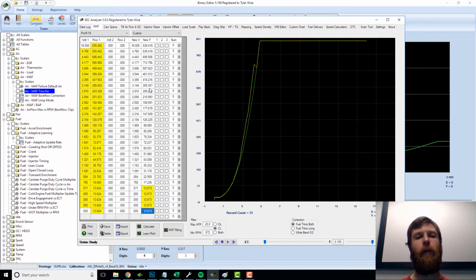So you're no longer running at 14.64 or thereabout, and that's all your factory oxygen sensors are capable of understanding and reading. So when you're in heavy throttle conditions, those sensors can't help you tune anyway. That's the whole reason you need a wideband oxygen sensor that can read that full range of air to fuel ratios that you're potentially commanding, to give you some better data.